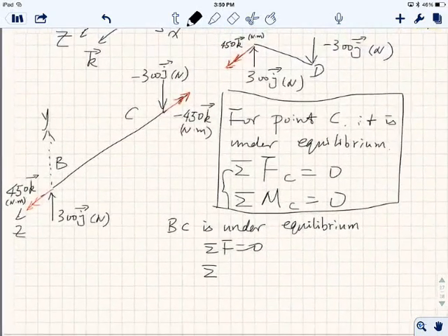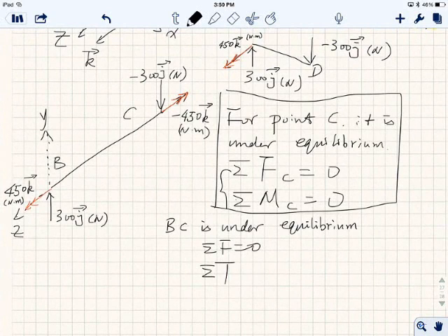All right. So when we say torque, we use T. We don't use bending moment anymore, all right? So summation T equal to 0. Therefore, we get these two numbers, right? Now, there's nothing I need to write over here because we are already familiar with the free body diagram. So that's why I write out this number directly. But you should know why it's 300, right? Because summation F is 0. Therefore, it's 300. Just different direction, okay? All right. We should be good, huh?